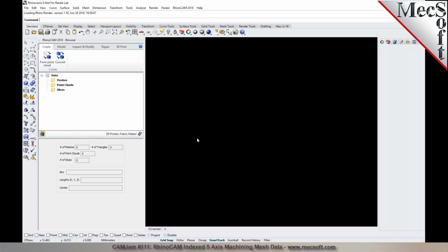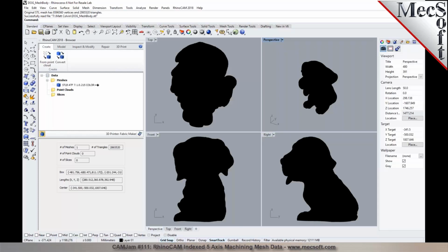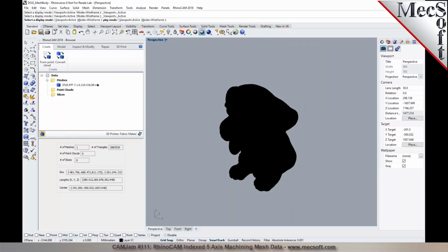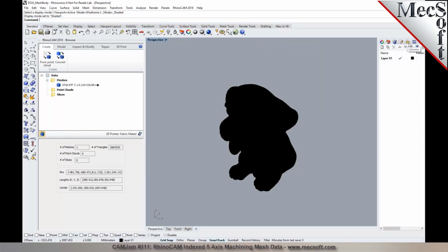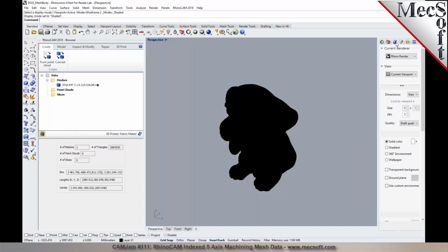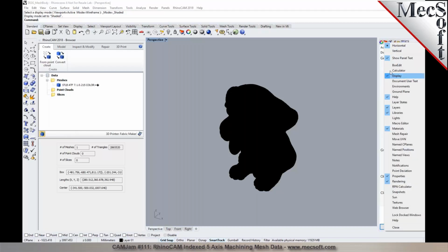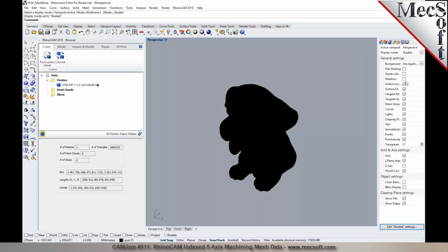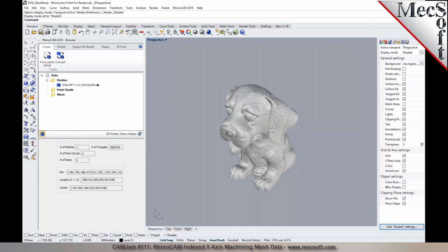And then can we set the document unit to inches though? Okay, so I will have to scale it back to inches because STL is typically unitless. It doesn't have any units tied to it when you have a mesh geometry. So once we import the file, we can switch it to inches. So if you go ahead and maximize this in here, let me also go to the display tab and hide the wires on the mesh, so it makes it easier to see it.